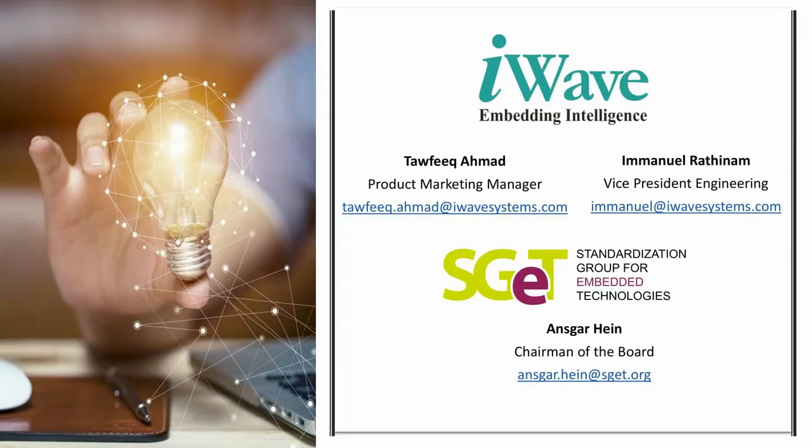The third question is from Kenji. Does OSM specify the level of ruggedness, vibration, etc. for reliability? No, actually there is no such thing. Since it is a BGA type, it depends upon how everyone designs the module. The specification defines three different options for the BGA balls, such as ENIG or solder balls. Whichever level of ruggedness you want, you can choose one, but the specification does not define the ruggedness you can bring in, or the ball type you should use at the bottom.